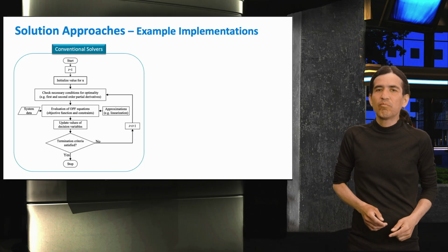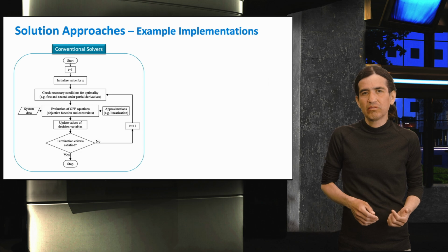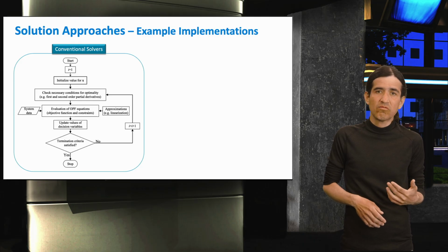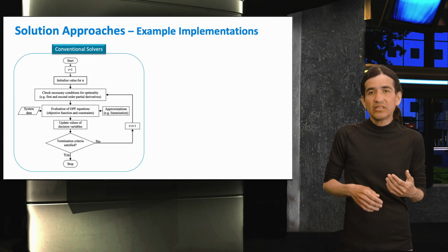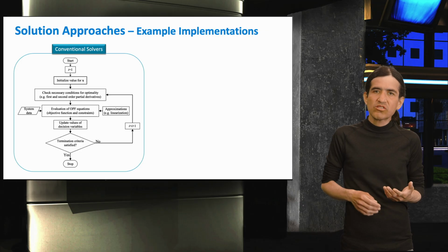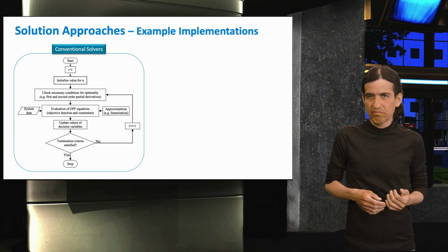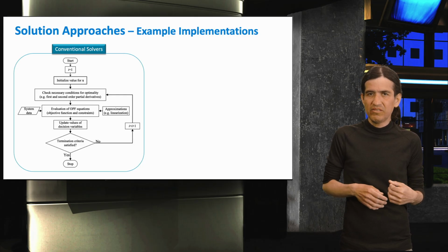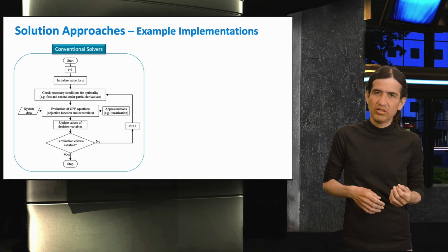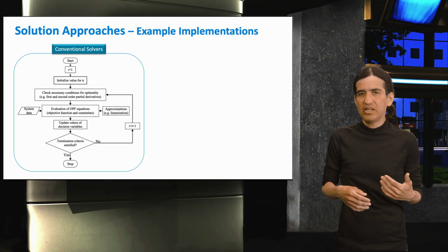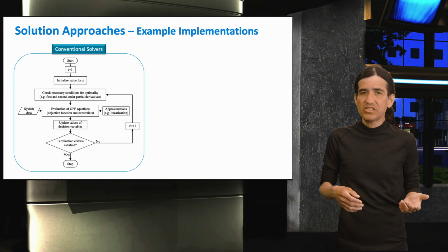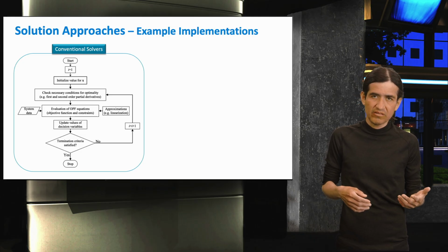Different solvers can be applied to the optimal power flow problem. For instance, a conventional optimization solver, like the interior point method or sequential quadratic programming, tackles the optimal power flow problem through a structured iterative procedure. First, the problem is formulated mathematically, defining the objective function, decision variables, and equality and inequality constraints. An initial feasible or non-feasible solution is then selected.